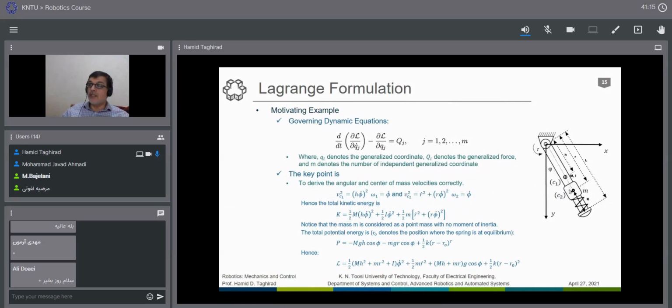We have two masses, so we have two kinetic energies. The first kinetic energy, let's consider the pendulum one. As we saw, we have two parts. One part is 1/2 m v squared, which we have already found, plus 1/2 I with respect to c times omega squared, where here omega squared is phi dot squared.